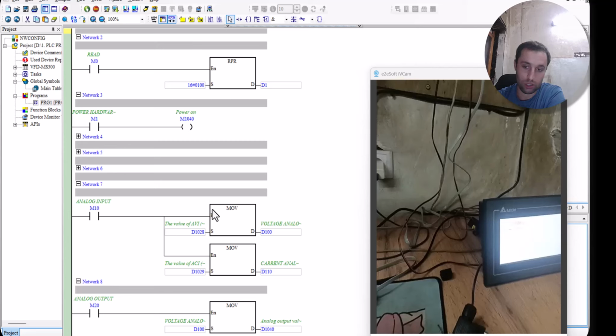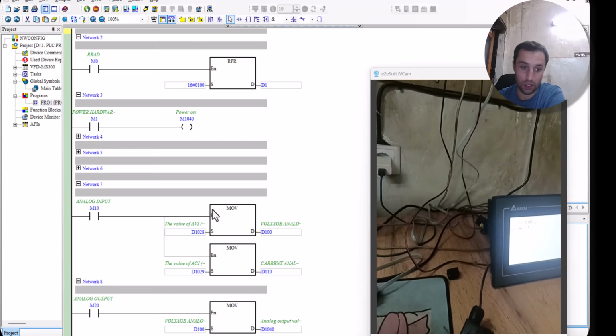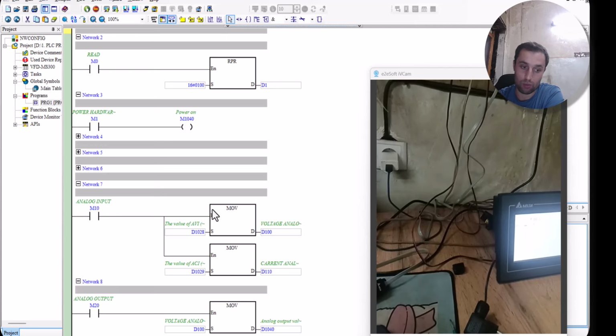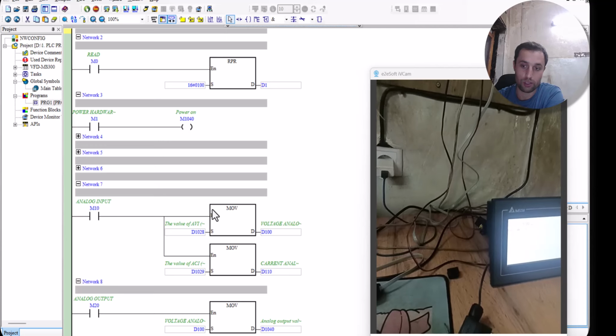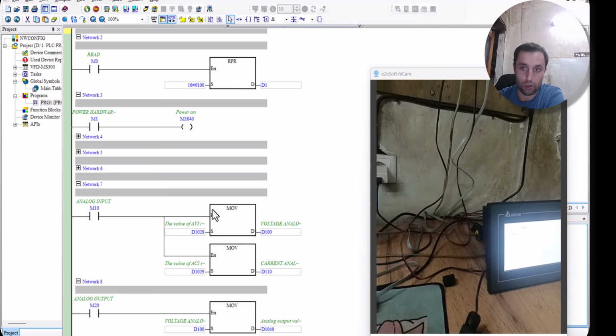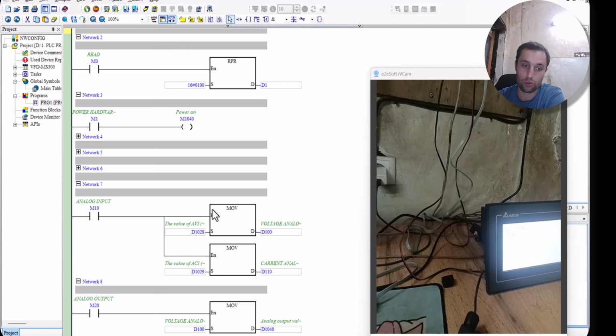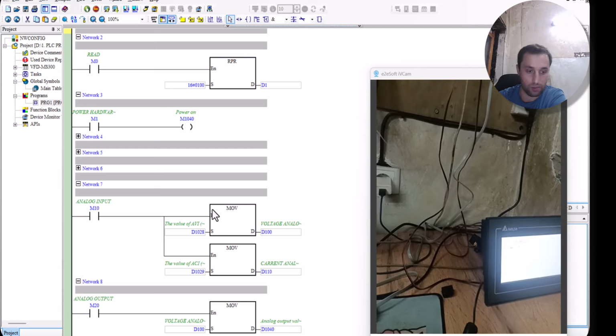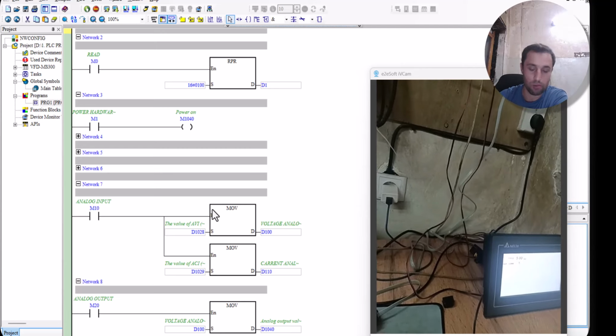together you cannot program or simulate, and now I cannot simulate because only at one time you can use the RS485 port for one reason, for example for the HMI. So for programming you cannot. If you want to program, you need to disconnect your HMI and then program. Okay, this was only about these things.